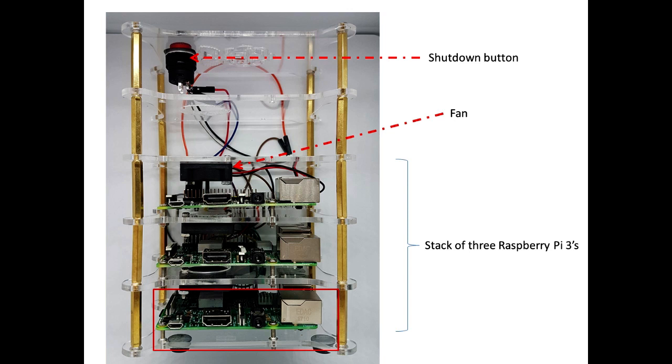But what I also added was a fan, or fans, because there's one on each layer, and also a shutdown button, because that's one thing that's lacking on the Raspberry Pi, the ability to safely shut it down. You have to log in and shut them down via software. Good old sudo shutdown and the likes. But what I've done here is just written a very simple script, and that script is engaged when we see a certain condition on one of the GPIO pins. We also use the other GPIO pins to control fans by measuring the temperature on each of the Raspberry Pis and then independently turning their fan on or off.